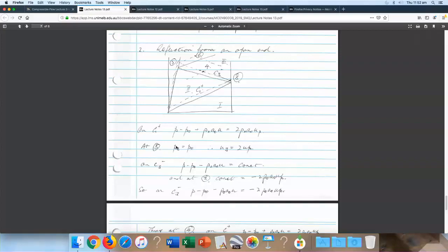You may be able to have a very long body and there's some high angle down here, and you put some sort of oblique shock wave, which is so strong that it satisfies the boundary conditions for the problem. But that's a hard problem. Once the flow is subsonic, it's a hard problem. So it's preferred to keep it supersonic then? Well, the trouble with keeping it supersonic, well, it's a two-edged sword. If you keep it supersonic, then you're going to want to have weak shock waves, because the stronger the shock, the more the entropy is going to be lost and the higher the drag. Right?